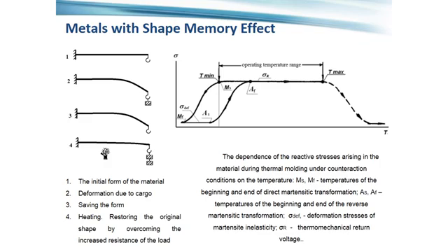Such properties of the alloys can be used, among other things, in neural networks, in adaptive control problems, and as algorithms of robots. As the conducted studies have shown, alloying titanium nickelide with third elements reduces the temperature of the martensitic transformation to cryogenic temperature. One of these is the alloys based on titanium nickelide doped with iron.